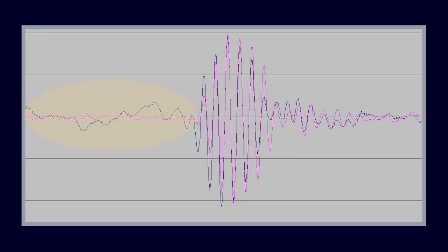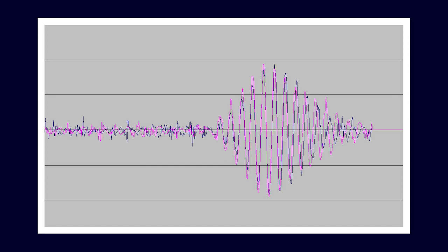Here's an example of when you may want to try increasing the received signal averaging. If you look at this image, there's a lot of baseline noise, and in this case, it's being caused by an upstream disturbance. Here's another situation where you may want to try increasing the received signal averaging. The random noise you see here at the baseline, sometimes we refer to this as asynchronous, will be lessened the higher the number we put for the received signal averaging.